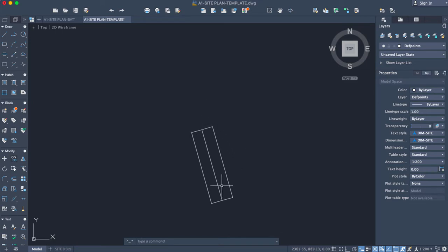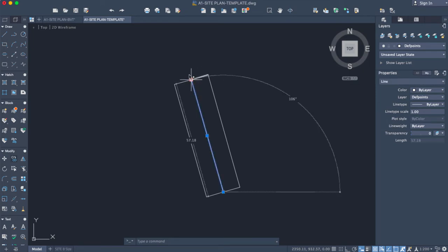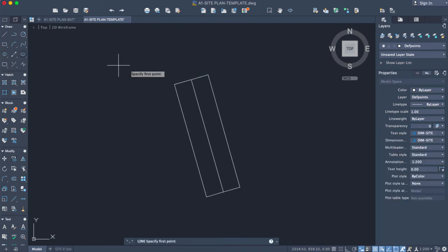And then as you see on the drawing, this line here, the property line is slightly extended above this line here. So you can simply select it and then extend it manually. You can stretch it. Or another option, I'll show you guys, you can simply draw a line right above there, just a random line, and then you can use the extend command. So the extend command, it's located under the trim command. So you can select extend and then try to extend these lines.